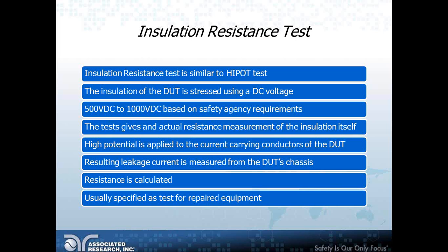Now, this test is similar to the Hipot test. It is basically the least commonly specified electrical safety test, but yet it can provide the user with some valuable information about the product being tested. Whereas the Hipot test provides a leakage current value, the insulation resistance test gives an actual resistance measurement of the insulation of the product itself.